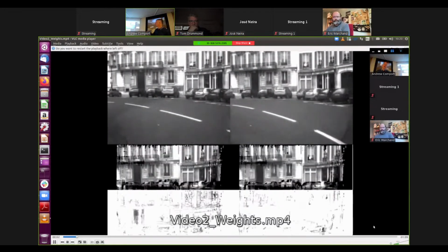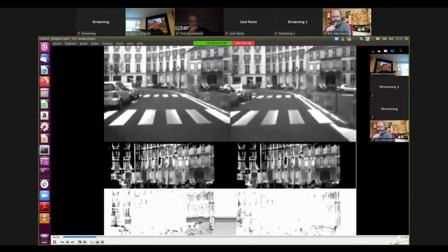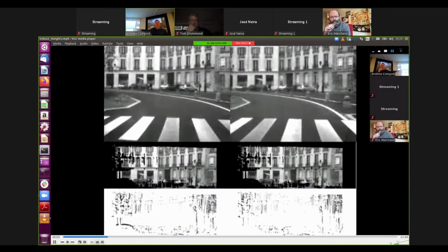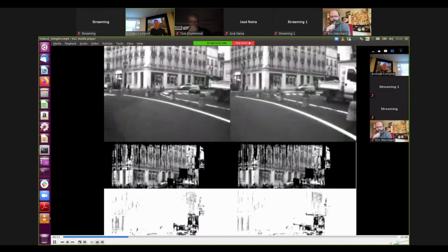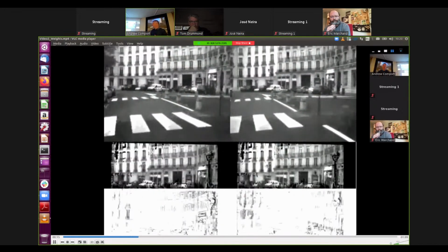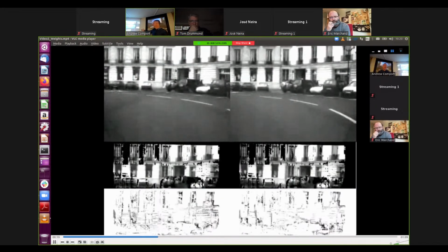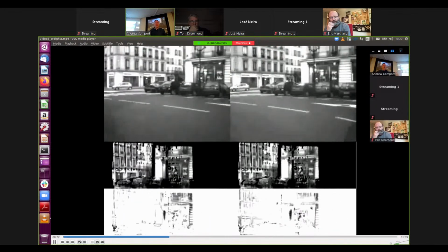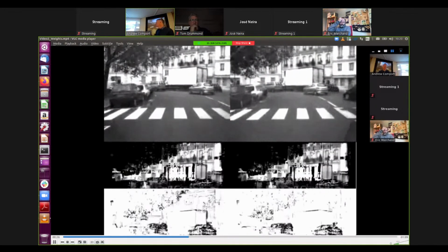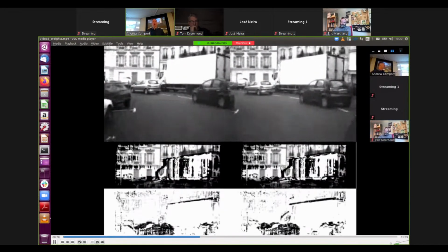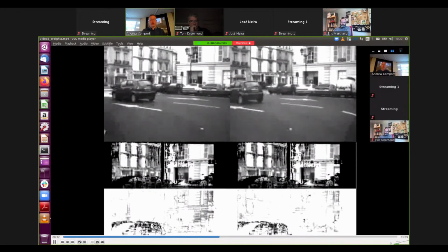So you have, again, the input images, and you can see the bottom images here are your warped images, or your transformed current view. And so the current view tries to stay static close to the reference image, and then it will jump. And when it jumps, it's when we're taking a new reference image. And you can see as we get out of the field of view, we need to add in more reference images to be able to map different parts of the environment. And at the bottom, we can see the robust weights. So anything that's black is being rejected from the estimation procedure.